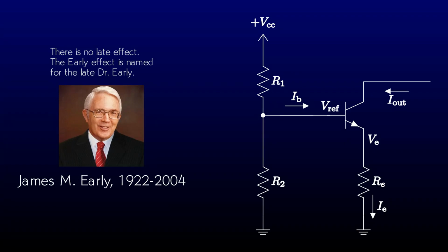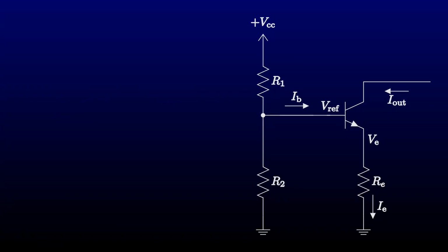This voltage-current relationship for the transistor is known as the Early effect. I might do an episode on it if we ever build a circuit that needs to take it into account. The intercept point of the line with the voltage axis is called the Early voltage. It's usually negative 100 volts or so for an NPN transistor. PNPs don't regulate current quite as well, and can have Early voltages in the positive 25 volt range. Enough about the Early effect. I'm off in the weeds here.